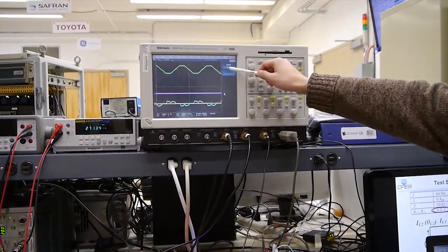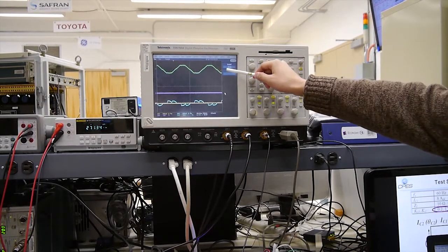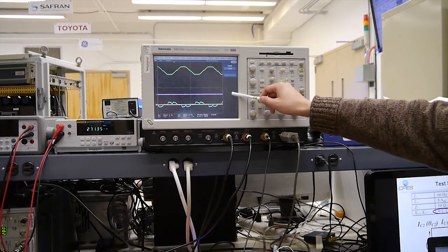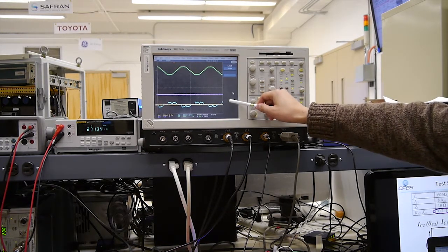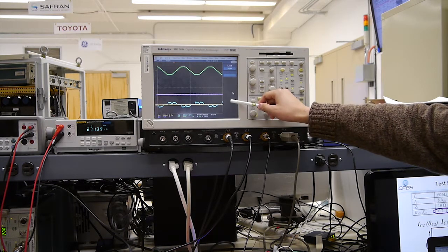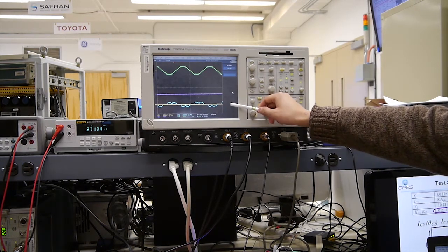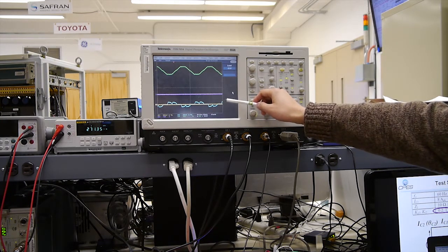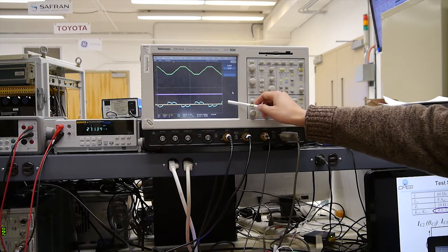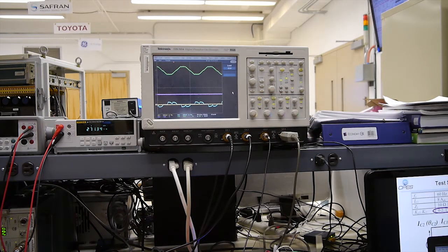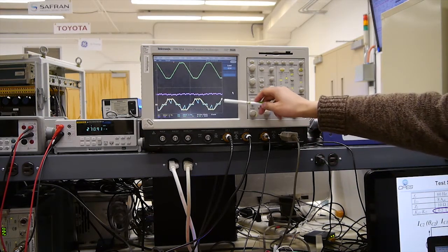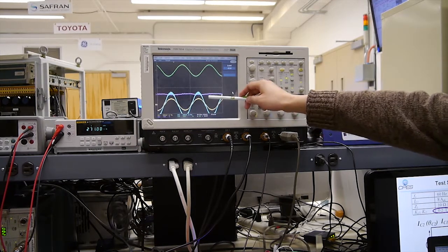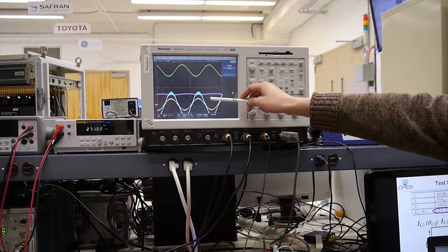The first green one is the PCC grid voltage, and the second one is the inverter output frequency, the PLL output frequency, and the blue one is the rectifier input current. The yellow one is the inverter current. Now the inverter is not running, but the rectifier is already connected to the PCC and is working in diode rectifier mode. When we start the first converter, you will see the inverter current is sinusoidal. And when the rectifier starts, the system becomes oscillating.